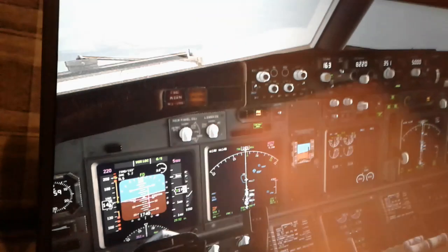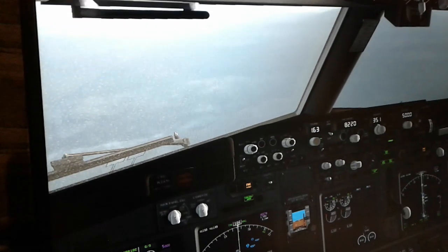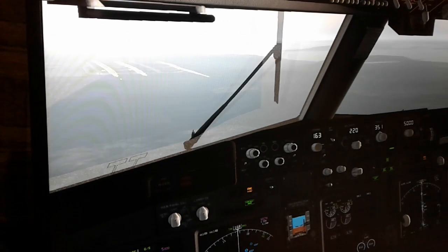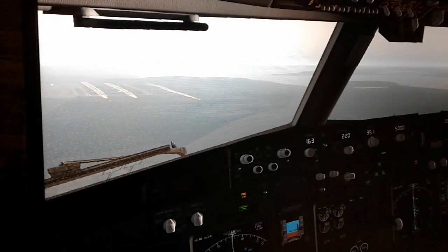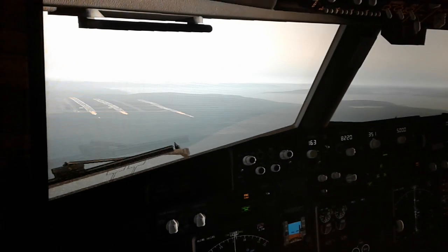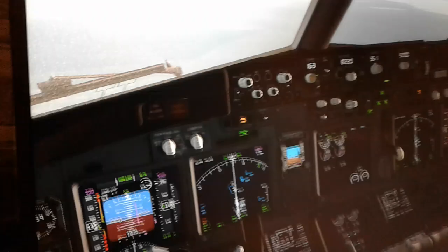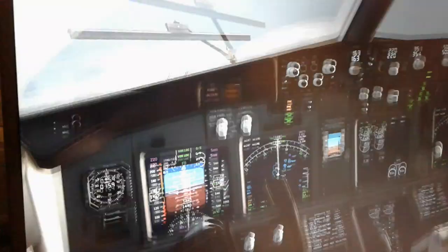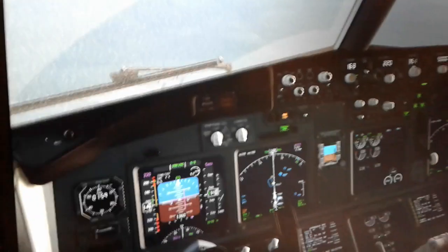Need to make it a little bit to the right using the ILS localizer. The wind is pushing us to the other side as we are approaching, so we need to use cross controls to realign the airplane with the runway.